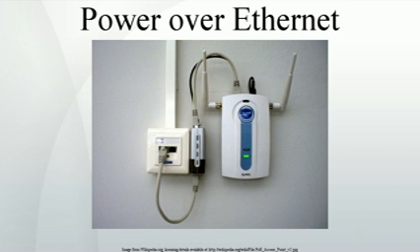Integrating EE and PoE. After integration with the IEEE 802.3az Energy Efficient Ethernet (EEE) standard, the energy management capabilities of the combined standard are expected to be good. Pre-standard integrations of EE and PoE, such as Marvell's ePoE outlined in a May 2011 white paper, claim to achieve a savings upwards of 3 watts per link, extremely significant across the tens of millions of new links shipped each year. These losses are especially significant as higher power devices come online. Marvell claims that